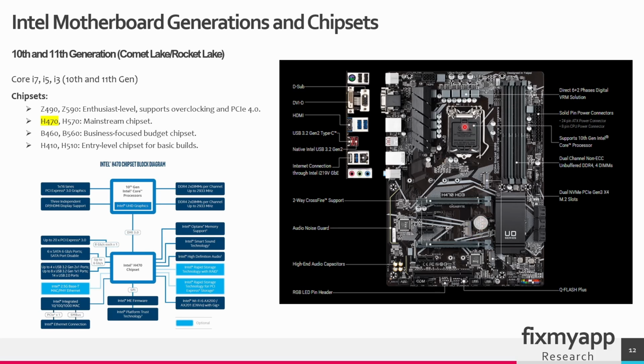We can identify the CPU part, the voltage regulator part, the RAM slot, the voltage regulators that will create voltages for the RAM, the back-end connectors, Super I/O chip, audio chip, M.2 slots, PCIe slots, the chipset that is under a heatsink, audio connectors, RGB connectors. Again, the physical layout is almost the same.